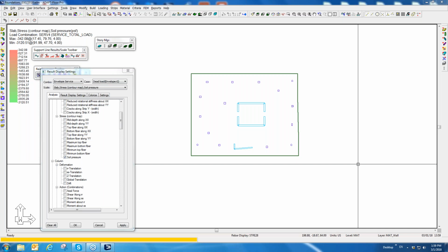If the calculated amount of reinforcement results in the ductility ratio, or the ductility threshold, being exceeded, the program in some cases will add, you could have a situation where it only adds tension rebar, which means that ductility is not exceeded. You could have a situation where the required amount of tension rebar exceeds ductility, so then we have to add compression rebar in order to drive the neutral axis up and maintain the ductility.